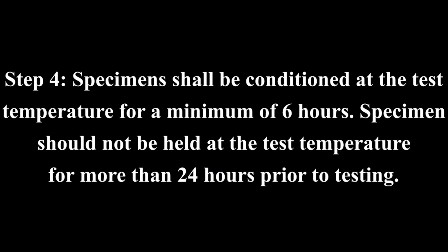Step 4. Specimens shall be conditioned at the test temperature for a minimum of 6 hours. Specimens should not be held at the testing temperature for more than 24 hours prior to testing.